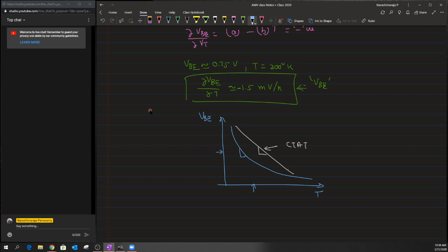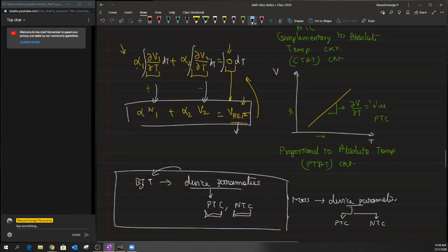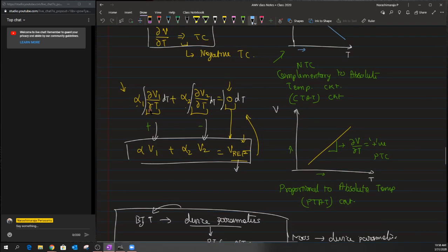So this creates some difficulty in realizing this particular function. Let me try to show that. Say, for example, if my V1 is basically my VB and this exhibits a variable temperature coefficient, then the value of alpha 1 that I am substituting here cannot be set appropriately. Its weight always changes, because the factor VB always changes with respect to temperature as well as the VB value that I am using to bias the circuit. So this creates some difficulty in defining this particular term.